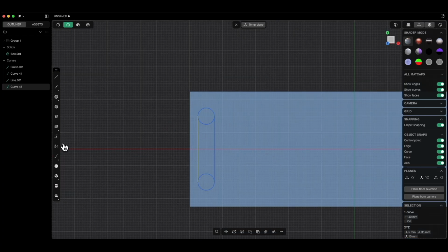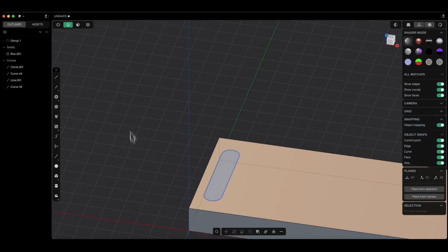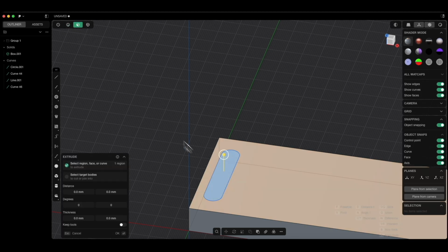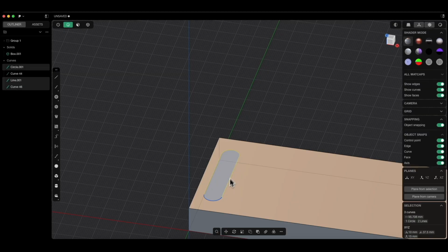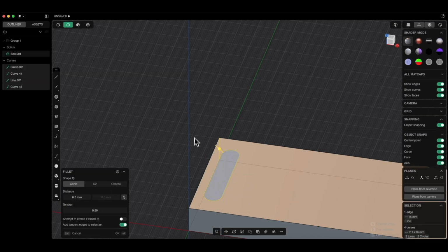Now I activate the trim command and trim these circle segments. At this point, these shapes are 4 separate lines. This doesn't prevent us from selecting the enclosed area, but if you want to join them, select the geometries you want to merge, either by holding Shift and clicking each one or by using a selection window, but be careful not to accidentally select other edges.